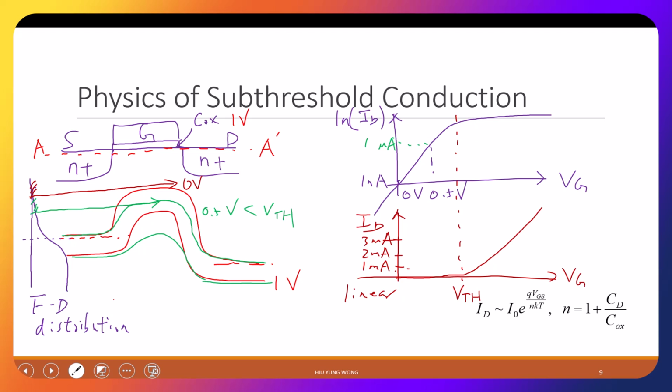That's why nowadays you won't turn off all the transistors at the same time. You actually have some special power saving strategy. Okay? But that is just at a circuit level. And that's why this is relevant. Okay? So now, if you want to model this in the subthreshold regime, you will model it as e to the power qV divided by nkT. Is this okay?